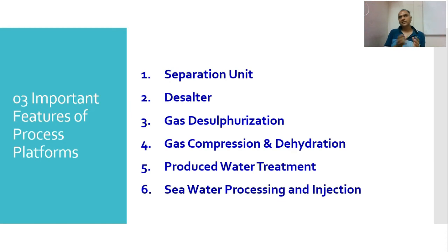Okay, so you can say that it is similar to that dead crude. Means if you pour that water, nothing will happen because there is no carbon dioxide dissolved in it to make it active. So same way is applicable for this dead crude also. That is why dead crude is very easy for handling, and for transferring we require it to be a dead crude only. Okay, so separation will not only remove the water, produced water and sand, but also the dissolved gas. That is, we will make the live crude into a dead crude. That is one thing. So this is a part of separation.